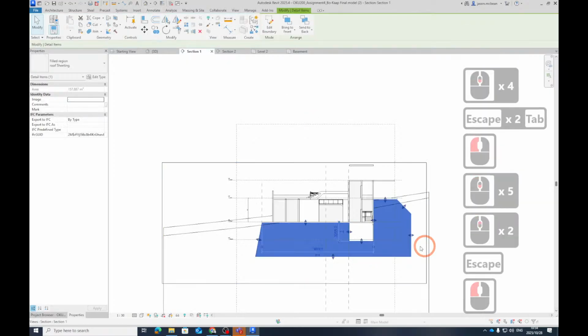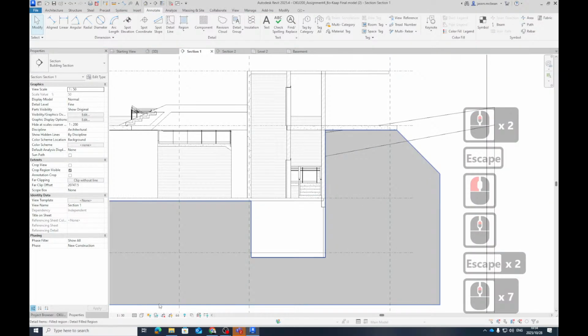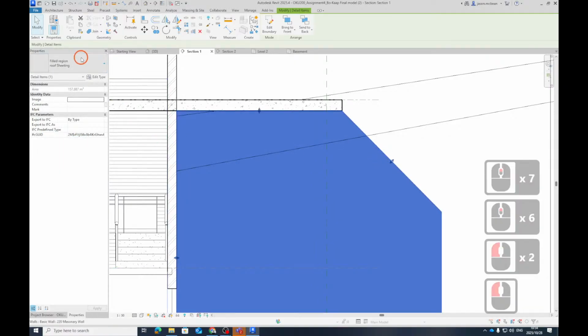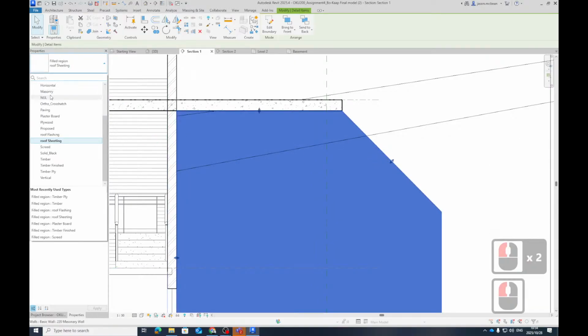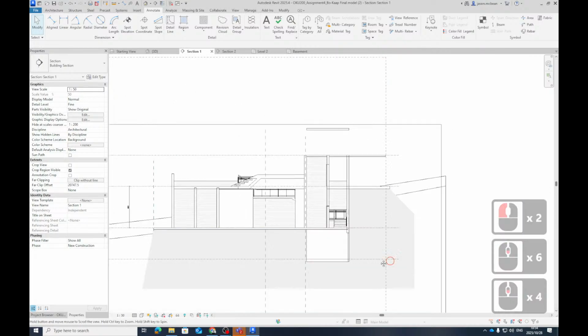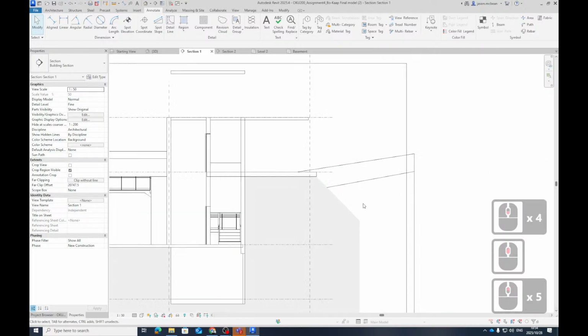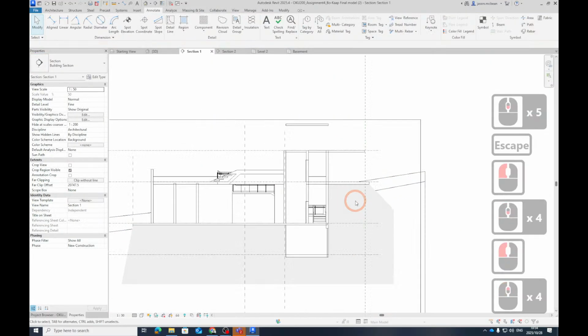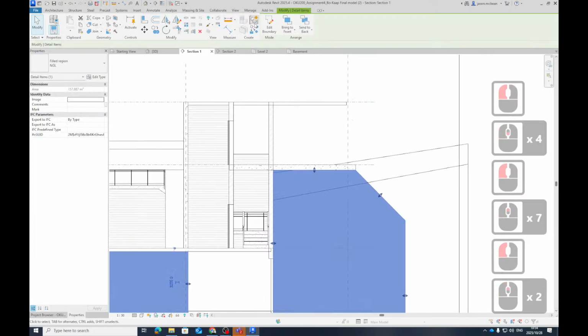Go finish. Now, I don't know what I've selected in the meantime. So what fill is this? This fill is roof sheeting, but if I go NGL, now you see there's no line work here because it's invisible. So you want to blend that in with your natural ground line, but hide this now. You don't need it anymore because you can now go and say edit boundary.